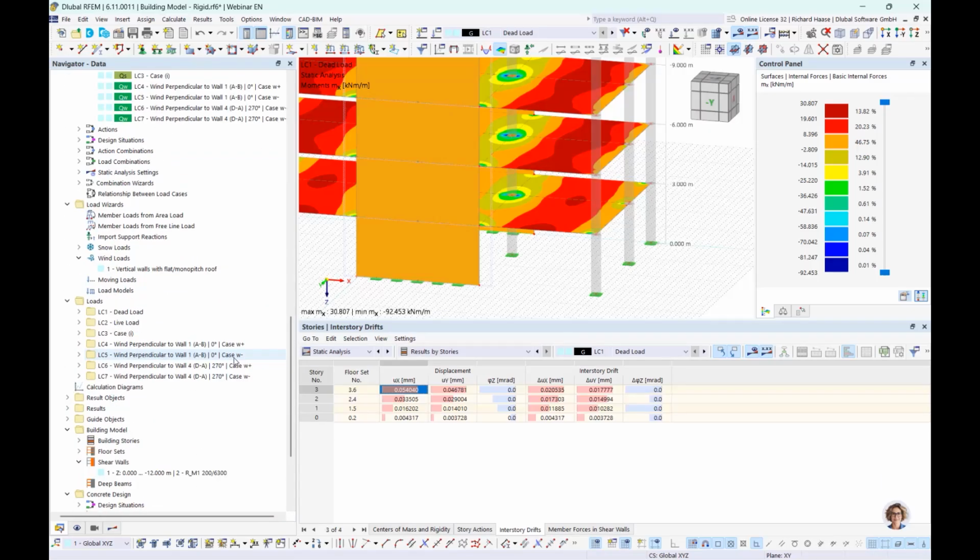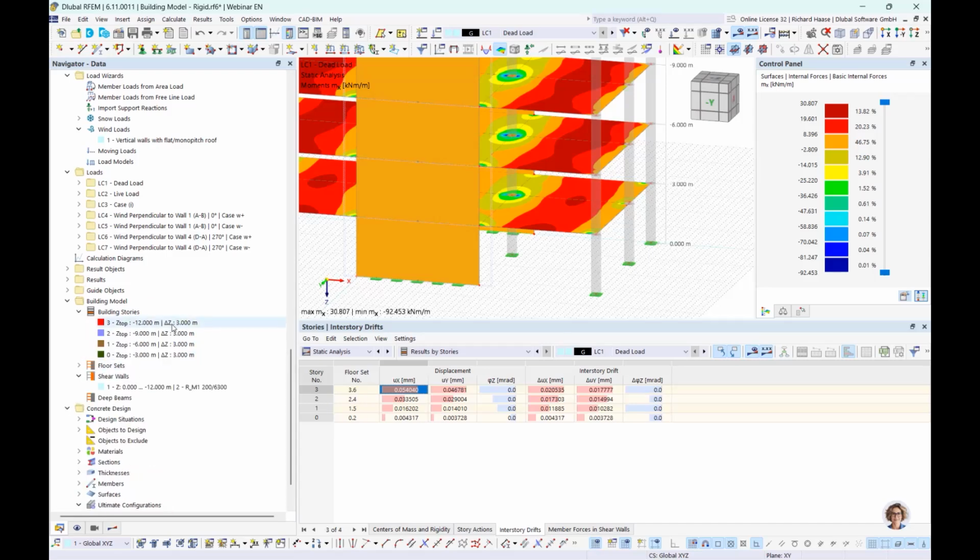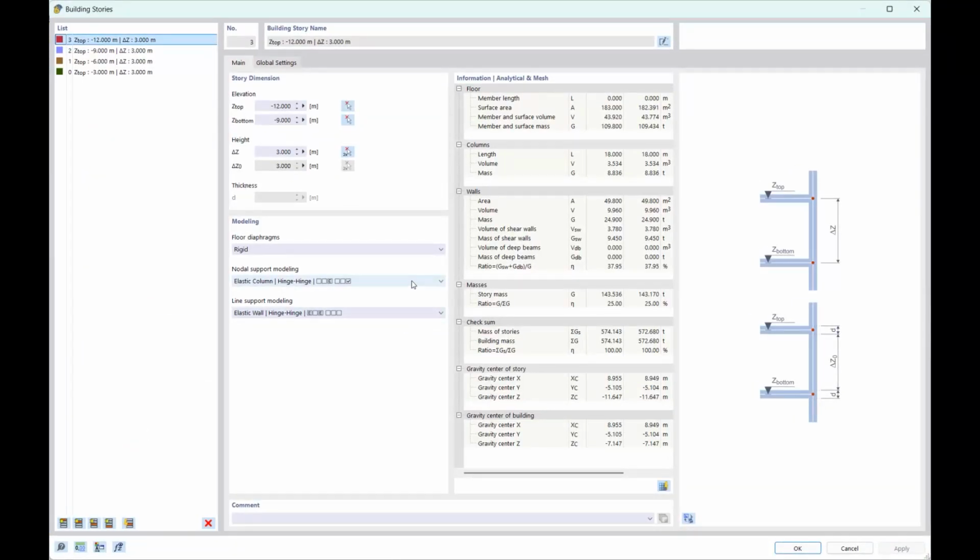We also have two additional story types. I want to say something about it too. Here are rigid and semi-rigid. Then we also have without stiffness, and that's really only a slab without stiffness, which is only load transfer, and in some cases this could be usable.